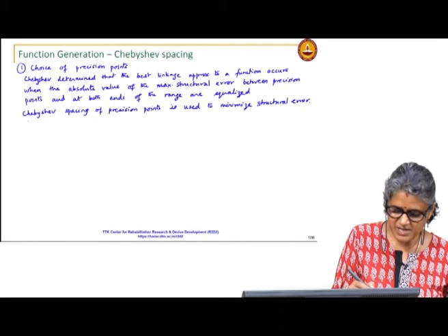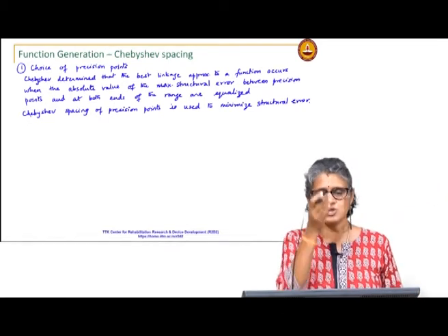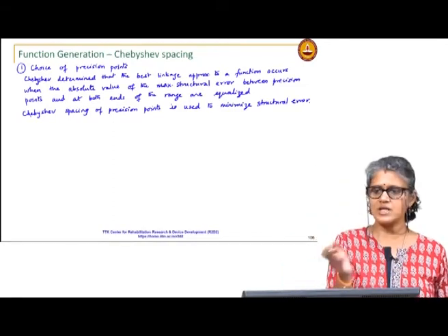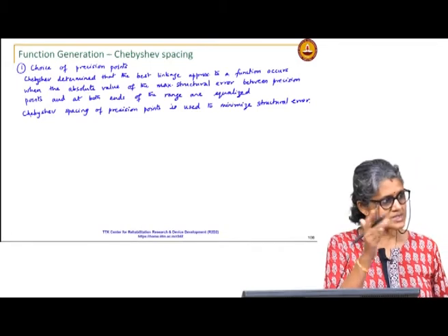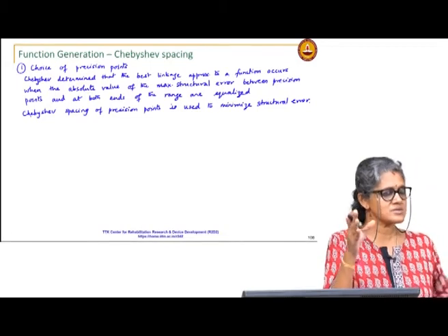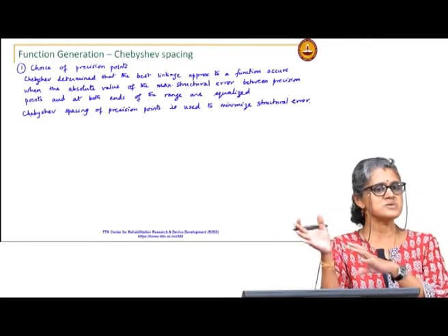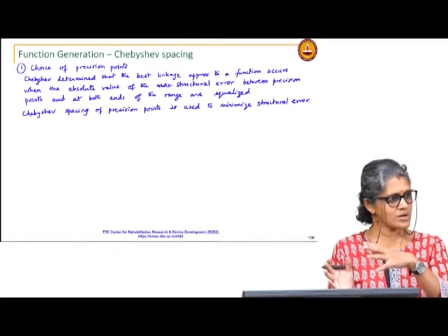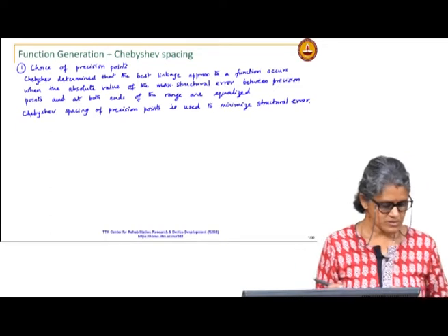And for function generation we usually measure the angles from the first. So, you can always take your phi naught equal to 0 without any loss of generality, because in function generation you are only concerned with angular displacements. Once you design the linkage, that relationship is maintained regardless of whether you scale up or down the linkage or reorient the linkage, okay.